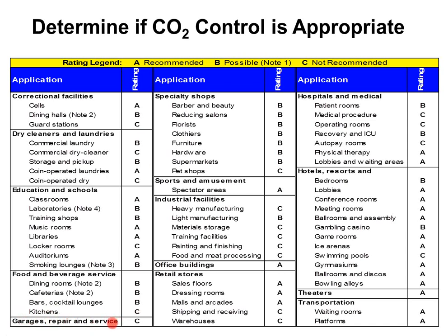Parking garages and vehicle maintenance bays, same thing. We can do DCV, and it's very common. We just don't do CO2 DCV. We do CO, carbon monoxide, because that's what the vehicles are, quote-unquote, exhaling, if you will. And if you have a diesel place, then we do NO2 in addition to the CO, but not CO2 sensors.